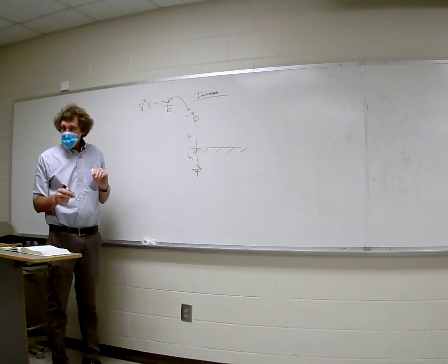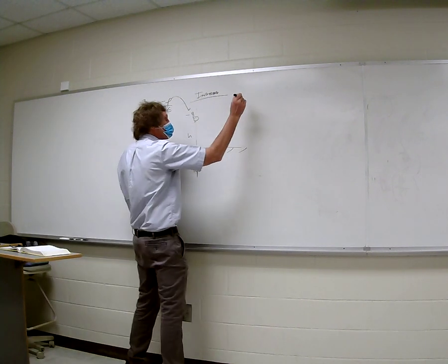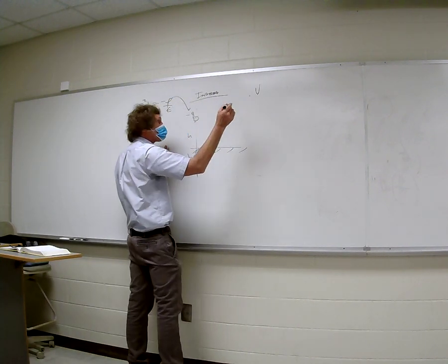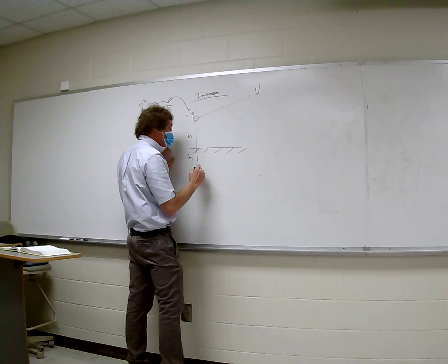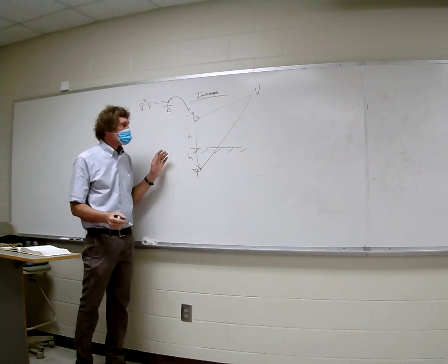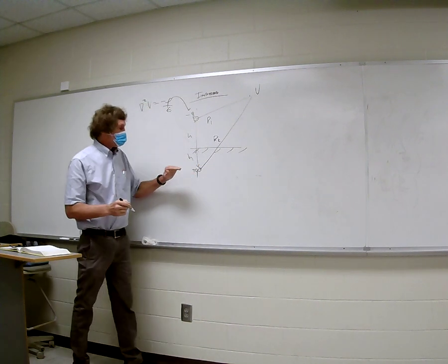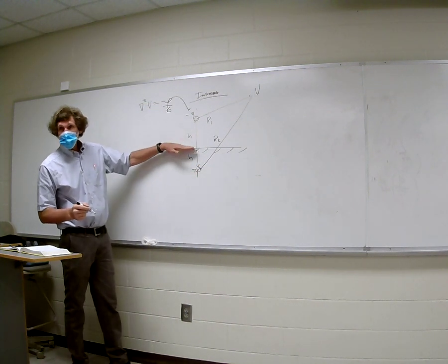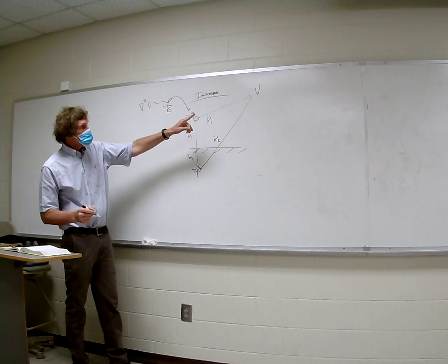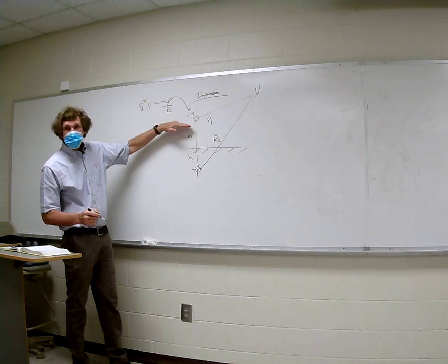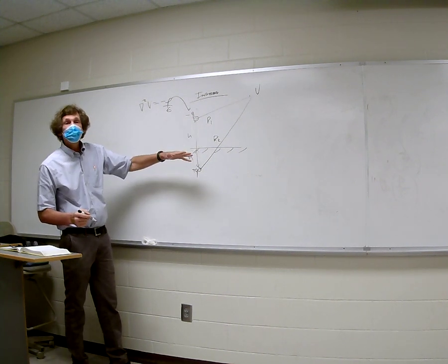So this way, the only thing you have to do is, if you want the voltage or electric field out here, you simply look at these two charge sources at distance R1 and R2. Find the voltage caused by this charge as if the ground plane is removed, find the voltage caused by the other charge as if the ground plane is removed, and add it together.